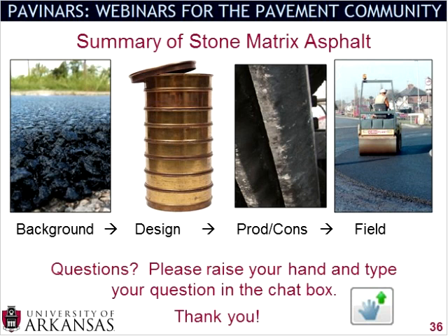But I think that the beauty of SMA is if material does fill into there, it doesn't necessarily compromise the material itself, the filling, but the side effects could. So if you start getting perhaps clay in there, and then it rains, that clay might want to expand, and expanding material within your SMA could cause problems. So I think that keeping those voids clear is important. And I apologize, I didn't look over that at all, but I'm sure there are technologies out there where you can actually keep those voids clear. That would probably be an added cost that, if you're looking into doing it, you would definitely need to account for in your maintenance strategies.